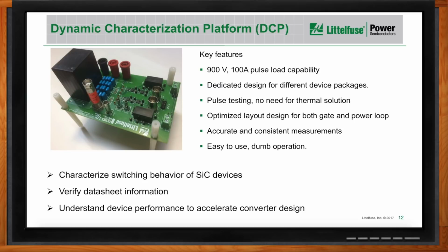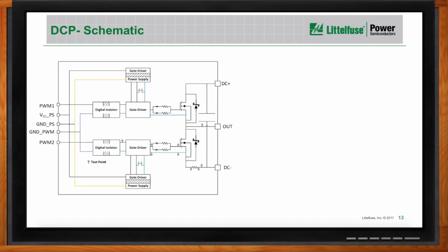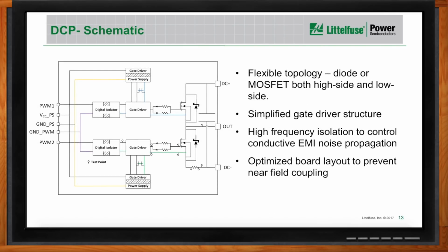Okay, that's cool. Have you got a schematic for this thing? Yeah, this is the one. For this dev kit, we have a half-bridge configuration for the power stage where the user can characterize either diode or MOSFET or both, for either high side or low side. We also give two separate gate drivers for the high-side and low-side switches, which allow the user to switch devices at different positions. We use a very simplified gate drive structure to allow customers to understand the switching function of the devices in a straightforward way.